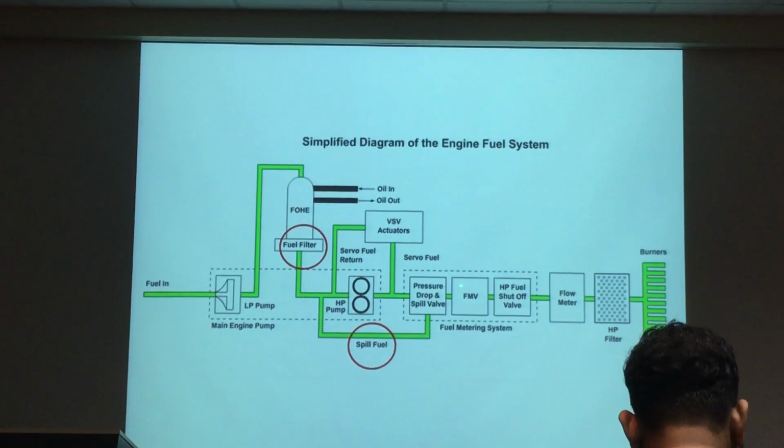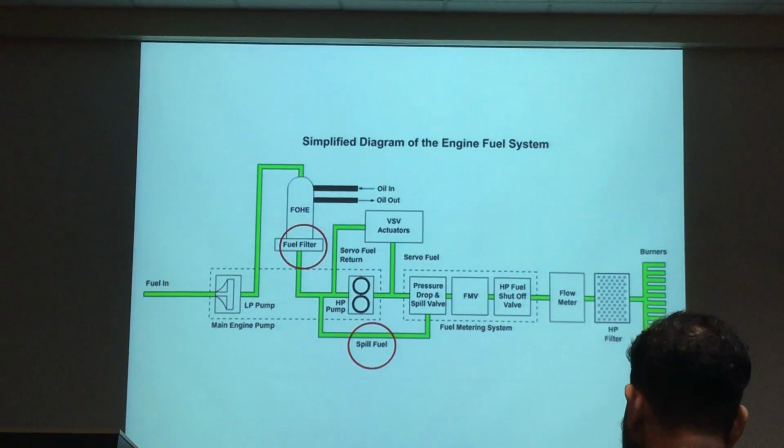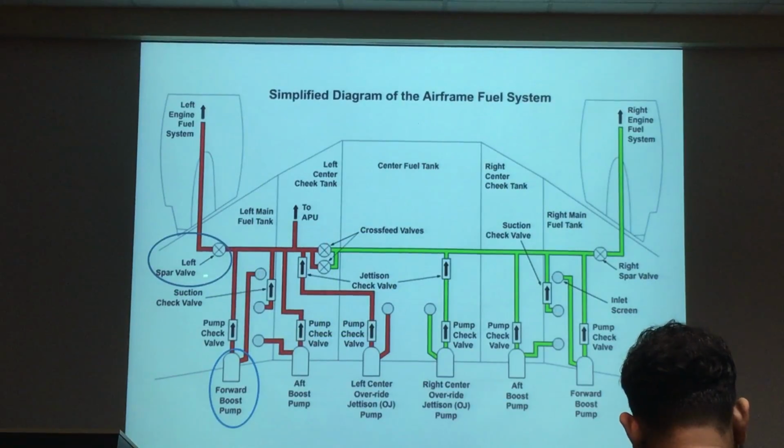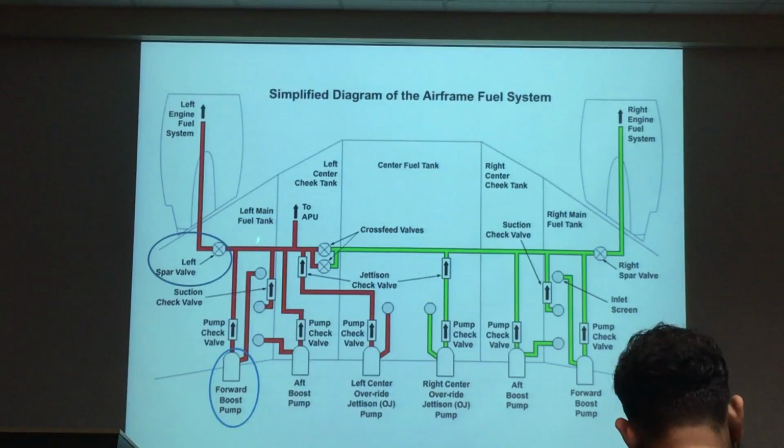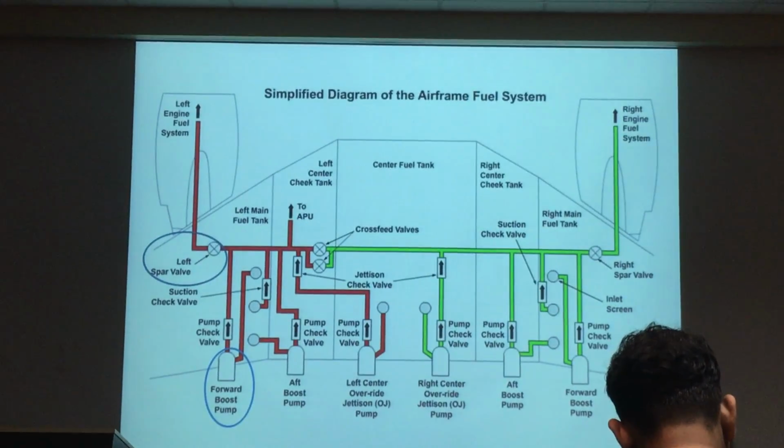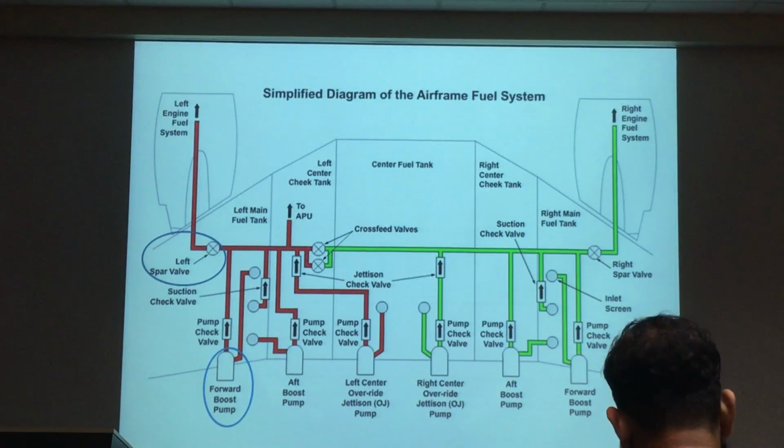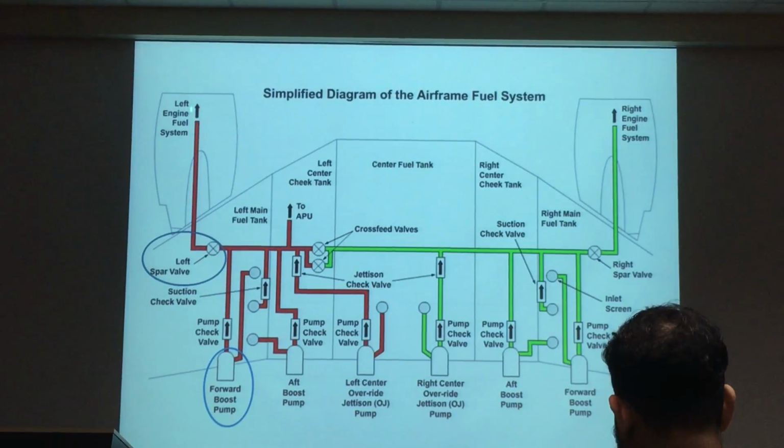If the HP cock fails, the emergency shutdown is done by the LP cock, done by here. Remember, this one is a mandatory requirement. This is emergency. Yeah? When you pull the fire handle, it pulls this valve closed. Okay? So the engine will run until all the fuel here burns out, no more. Then the engine will shut down.